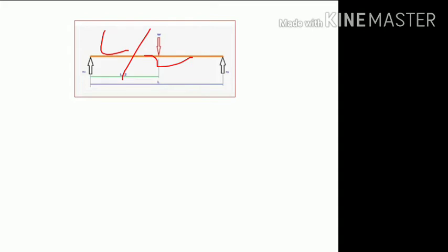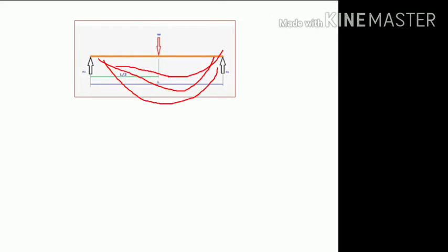Now in shearing force, due to the load W, the load W tries to shear the beam, meaning the load W tries to split the beam into two parts. This force is called the shearing force or shear force. Instead of shearing, the beam may also bend. So there are two things: one is the beam shearing into two halves, and another is the bending of the beam.